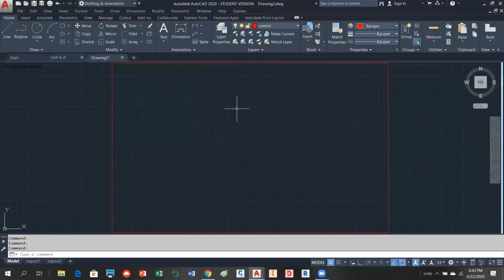Okay, so I'm going to go ahead. We're going to put control point 3 and control point 1 in. So I'm going to go into the line command. Now I'm skipping the whole boundary. You guys should know how to do that. But if you have questions, you can certainly pose them to me later. Okay. All right, so we're going to go into point 3. So at the line command, when it asks you first point, type in 2511, comma 7433, and hit enter. You should notice it's kind of in the upper left-hand side of your rectangle.